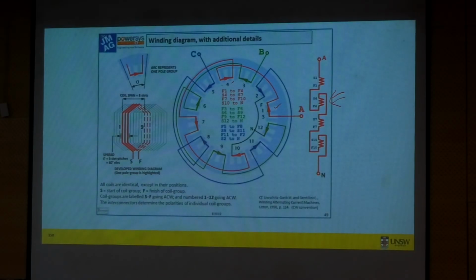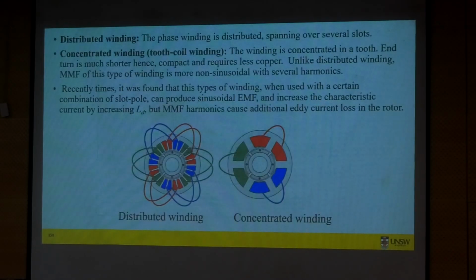And the other thing is, in the case of concentrated winding, we mentioned this. Compare the concentrated winding and distributed winding here, these two pictures. Both of these windings have slots per phase of 2, right? The red color one, you can see in both cases slots per phase is 2, but for concentrated winding it is so simple, and it requires a much smaller number of slots. So construction is easier, that's why concentrated winding is used.